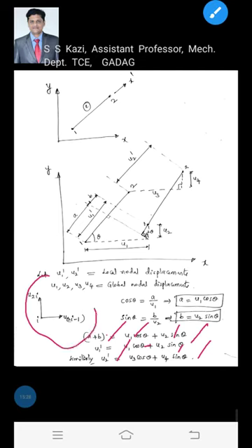And this I have shown is a numbering scheme for 2D problems. This is a 2D truss because at each node there are two unknowns: one is the x component of displacement, another is the y component of displacement. How do we go for the numbering? I indicates the node number. The x component will be u2i minus 1 and the y component will be u2i.